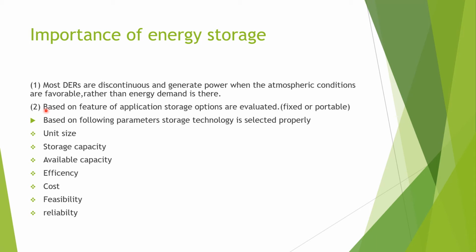So based on the following parameters, the storage technology is selected properly. First, the unit size of the storage device is chosen based on the applications. For example, large units support grid connected renewable distributed energy resources technologies. Then comes storage capacity. Storage capacity is the total energy available after complete charging. And then comes available capacity. It's the average value of output power based on the depth of discharge.